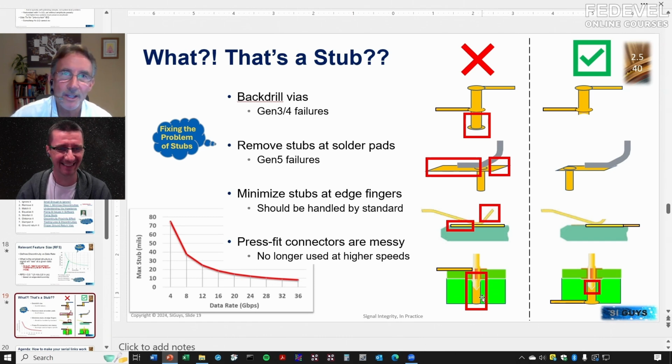Oh, right, right. Well, I watched the standards above around 20 gigabits per second. It's all surface mount connectors, you know. But the big backplanes used to use the big press fits, right? And so, boy, we spent a lot of time chasing those problems. Okay, so for those, very high speed, SMD, no through holes, please. Yes, right, correct. Very good.